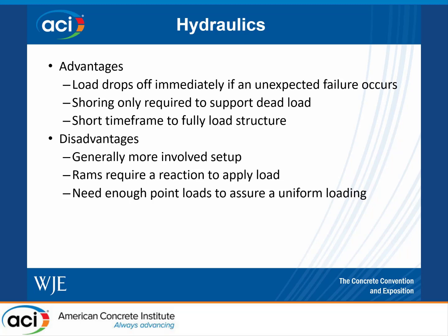Primarily, your shoring will only need to support the dead load only. You can also apply the load very quickly using hydraulics, which is a significant advantage. Typically, we have a subcontractor assisting us with all of these tests, and you have a large number of laborers on site. So anytime that you can reduce the time associated with loading or unloading the structure, you can save a lot of cost.